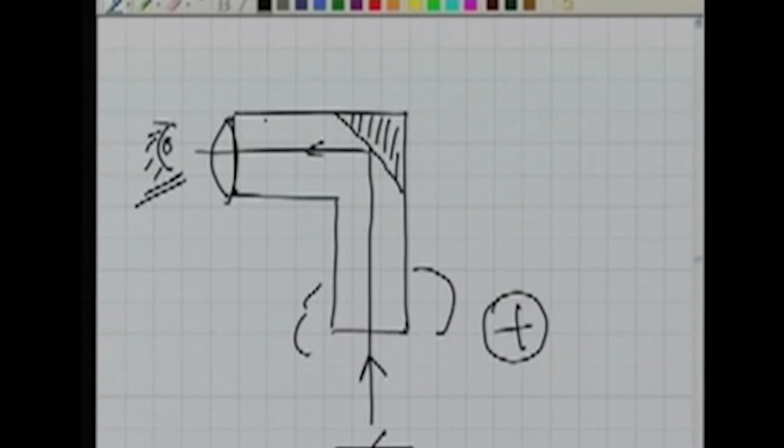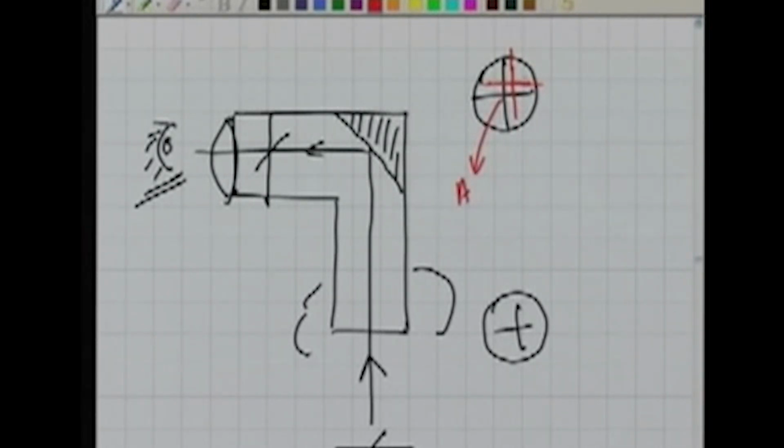Now here in the eyepiece of the optical plummet, again we have a cross wire. So the cross wire of the optical plummet, which may look like this, and the mark there in the ground. Let's say the red line indicates the station there in the ground. This is the station. What our job is, we want to align these 2 points, point A and point B. Point A is the center of the cross wire here. Point B is the center of the mark there at the station, and we want to align these two.